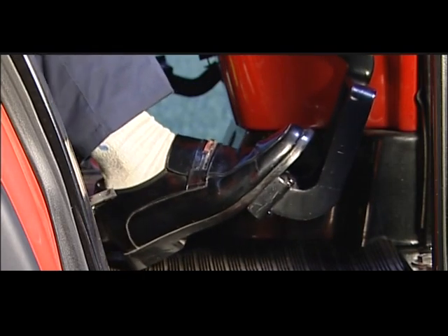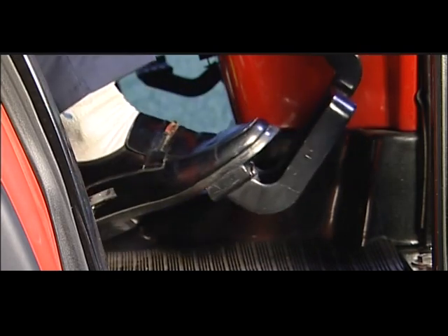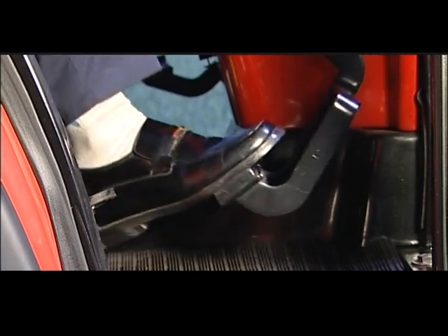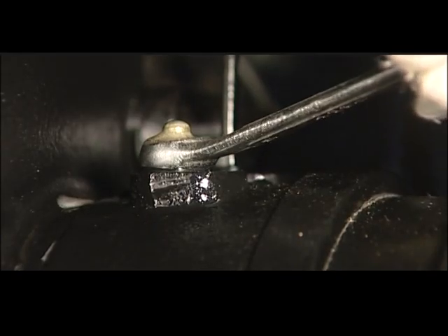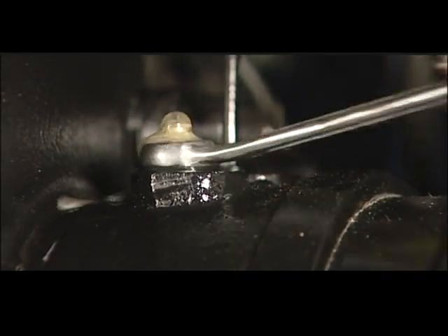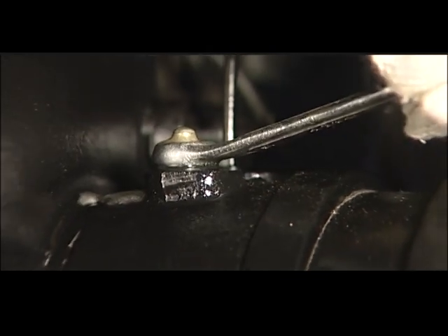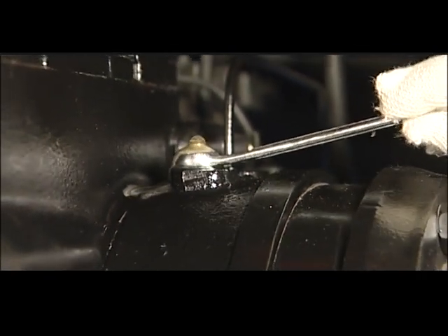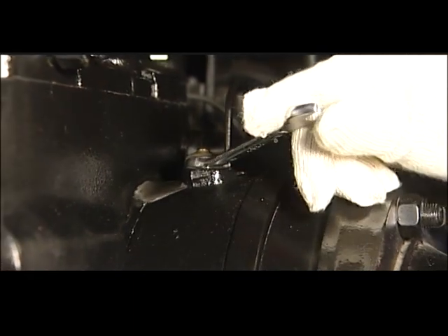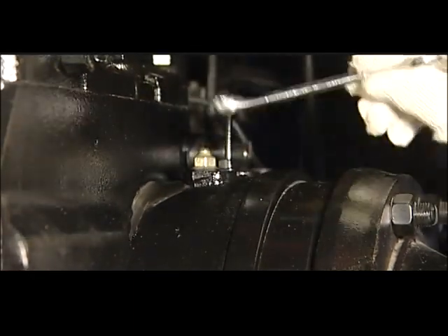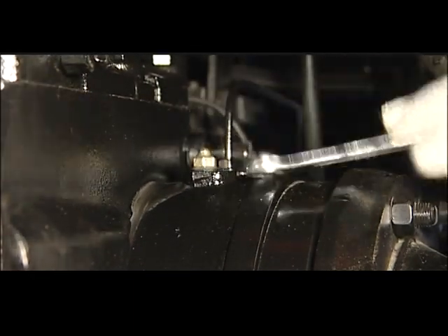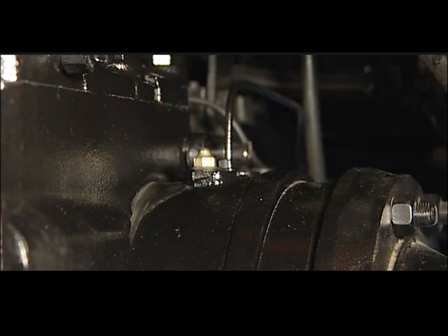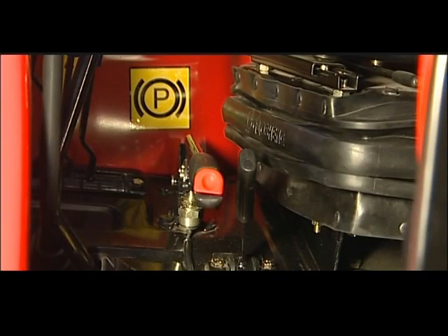One slowly depress the left brake pedal to the end, unable to create the braking pressure. The other unscrews the air bleed plug by half circle so that the oil can flow out while the one depresses the brake pedal. Tighten the air bleed plug. Repeat the above movements until the air bubble drains out with the overflow oil.